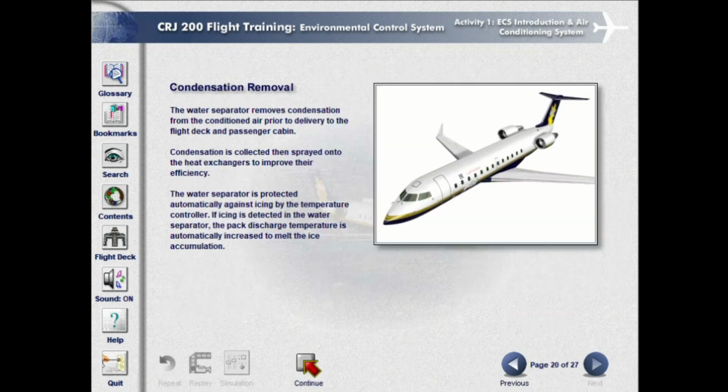Condensation removal. The water separator removes condensation from the conditioned air prior to delivery to the flight deck and passenger cabin. Condensation is collected, then sprayed onto the heat exchangers to improve their efficiency. The water separator is protected automatically against icing by the temperature controller. If icing is detected in the water separator, the pack discharge temperature is automatically increased to melt the ice accumulation.